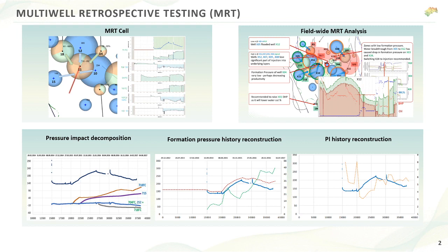We do it by building a mathematical model based on so-called unit transient responses. Every transient response is a mathematical function representing the pressure behavior in a well when another well is being launched with a unit rate.